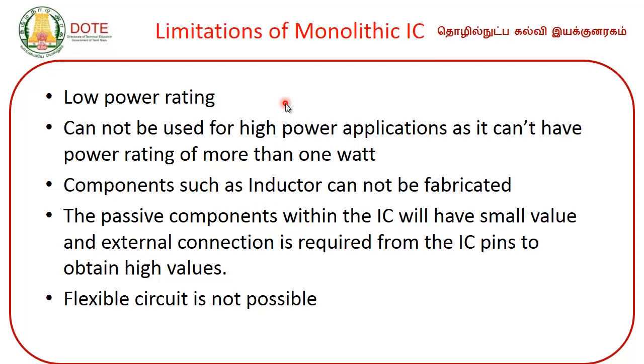but there are some disadvantages with monolithic IC, limitations. They are meant for low power ICs, that is, low power rating. For low power applications only, monolithic IC technology is suitable. It cannot be used for high power applications as it can't have a power rating of more than 1 watt, right. So, the circuit consumes less than 1 watt. For such circuits only this fabrication technology is suitable, right. For high power applications you have to go for hybrid IC.